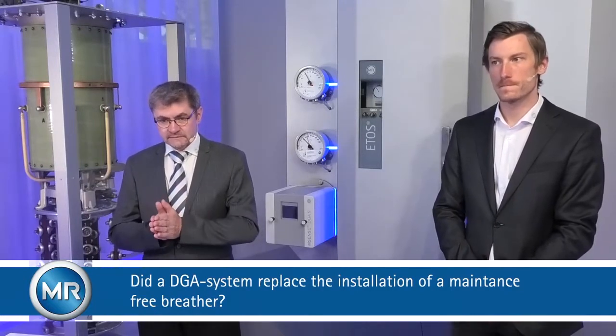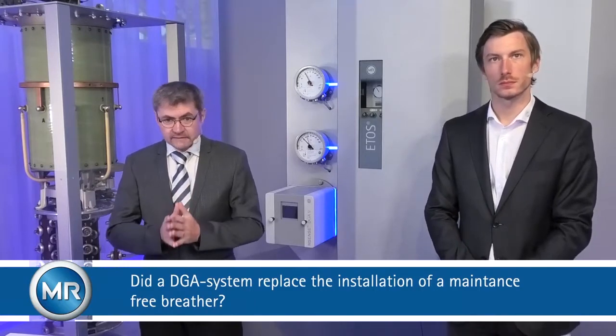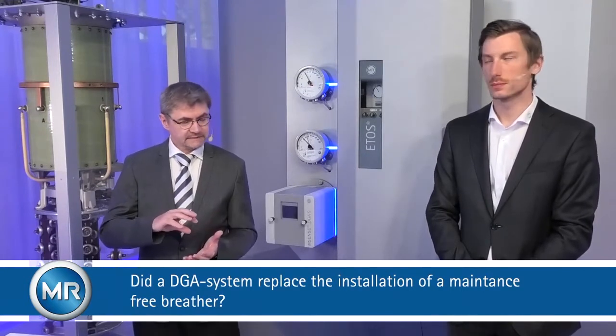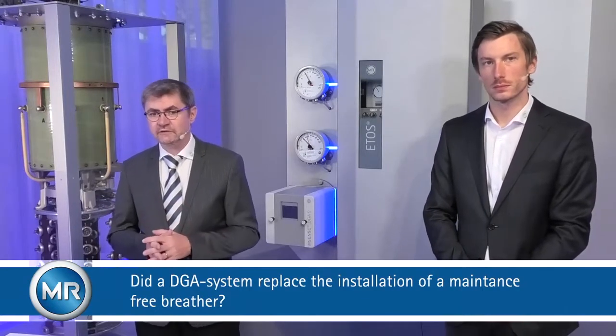The breather holds back the moisture from the outside, from the environment. And the breather assures more or less that your insulating material stays quite dry. The DGA systems analyze these parameters in the insulating oil.